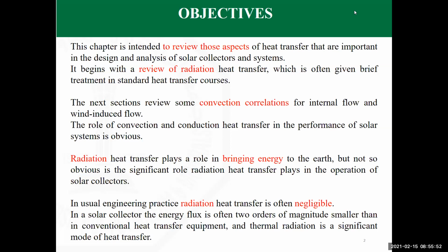To remind you, in heat transfer you first had to define whether the flow is laminar or turbulent, and whether it is developing or fully developed, hydrodynamically or thermally, and you had correlations for the criteria to determine that. In industry, we prefer turbulent flow, because turbulent flow is characterized by a high heat transfer coefficient. And normally this is what you need: you need to transfer as much heat as possible to the fluid. That's why we like turbulent flow.